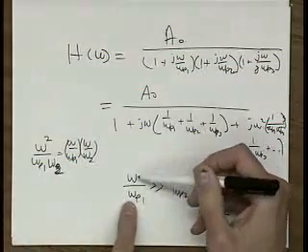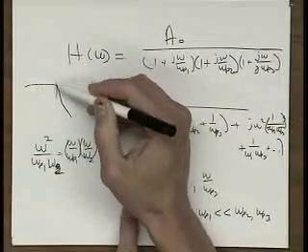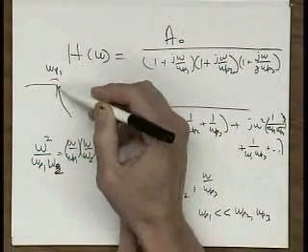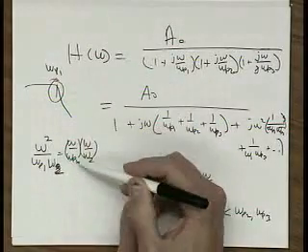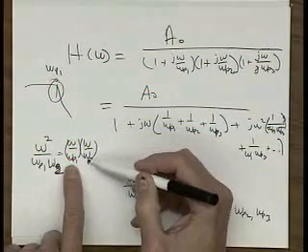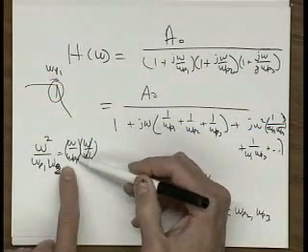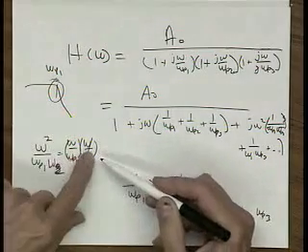So now if we have omega in the range of omega p1, let's say this is where omega p1 is, we're interested in frequencies at omega p1 and below. So we're looking at the lowest frequency pole. You can see that this factor here is going to be very small compared to this one. Even though this may be near unity, this is going to be very small.